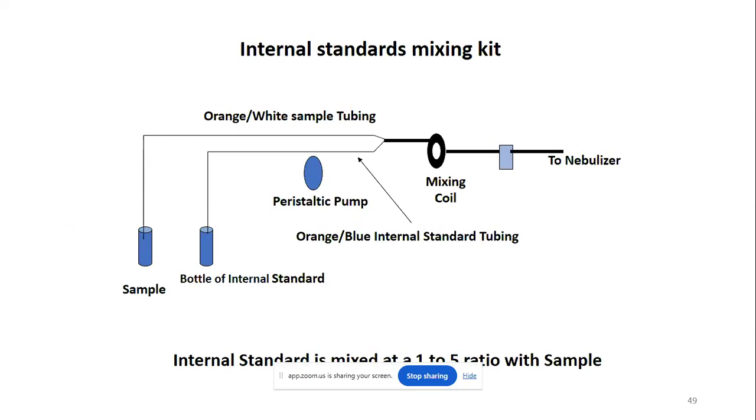So we know that we added 5 mg of copper in the sample. We check the concentration of copper along with the other metal ions in the results. We know the copper we added is 5 mg per liter, so we see what the instrument is showing. Likewise, this is the internal standard mixing.